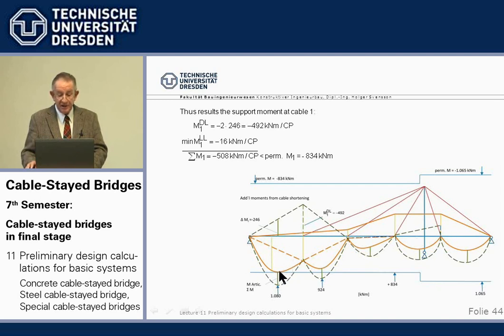And we see now here, we are just at the 834. Here we have something left. Well, that's not bad. Leaves us a little moment stress capacity. And then we shift these third part of moments due to cable shortening a little bit higher. We are free. We can choose any moment by cable shortening we want. N cables, n times statically indeterminate, n moments to choose.